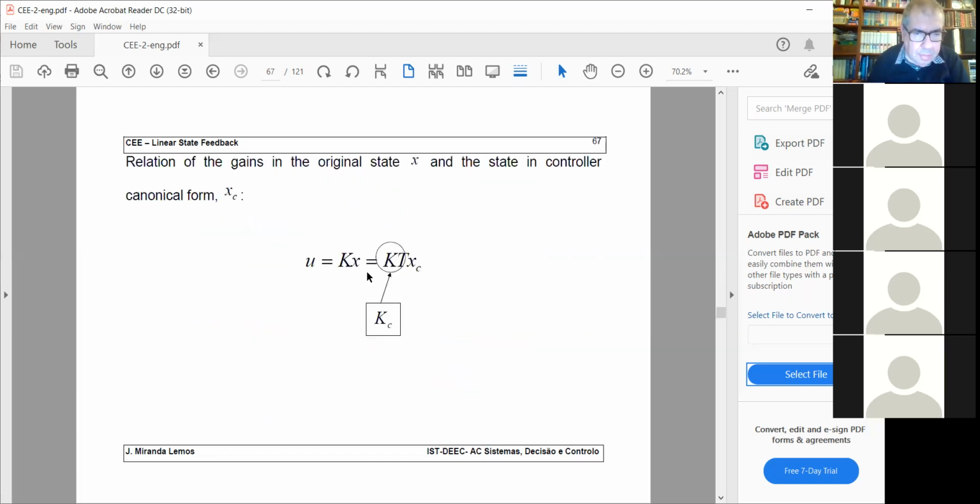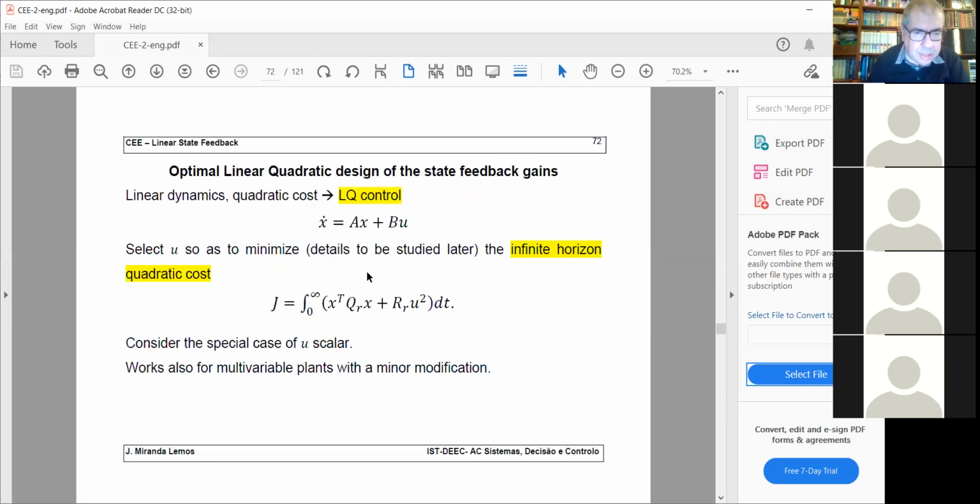So I would like now to discuss with you where can I place the poles? So what is your suggestion to place the poles? Remember that the polynomial alpha is made by terms which are s minus each of the values of the poles that you want to specify.